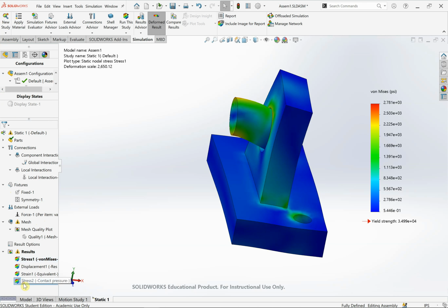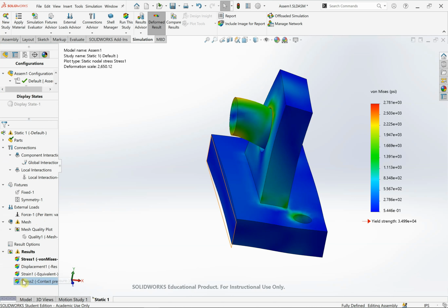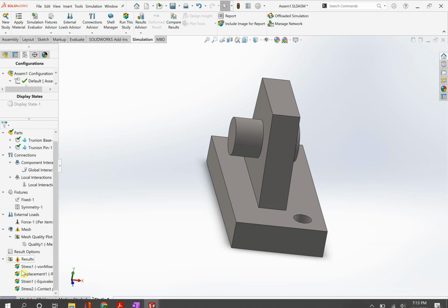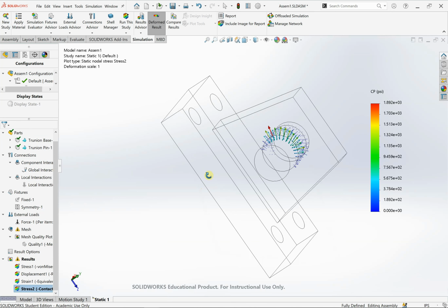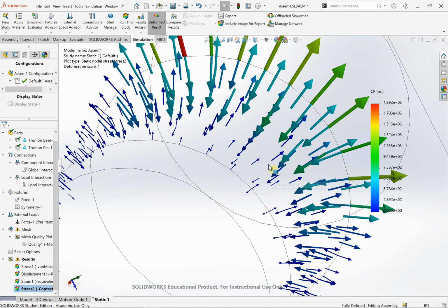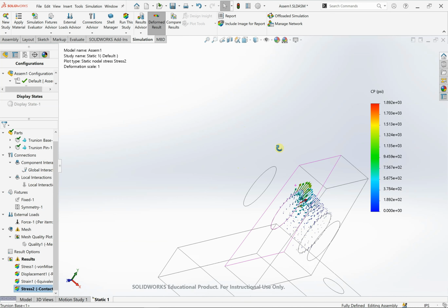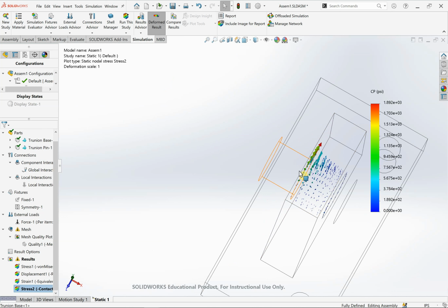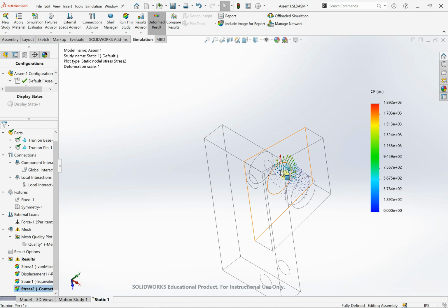But yes, this contact pressure plot is showing us the magnitude and direction of the contact pressure for our contact. So we can rotate it around and again see how it's larger where we applied our force on the outside and it's being pulled upwards with that 60-degree angle that was defined.